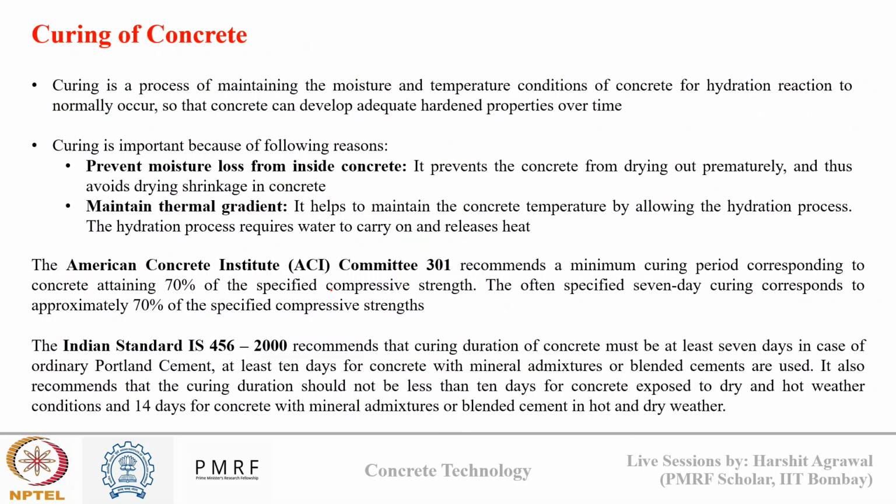After pouring and compaction, the final step is curing. Curing is the process to maintain the moisture and temperature condition of concrete for the hydration reaction, so that concrete can develop adequate hardened properties over time. We have seen earlier also that the curing period is the period in which my concrete gains strength.